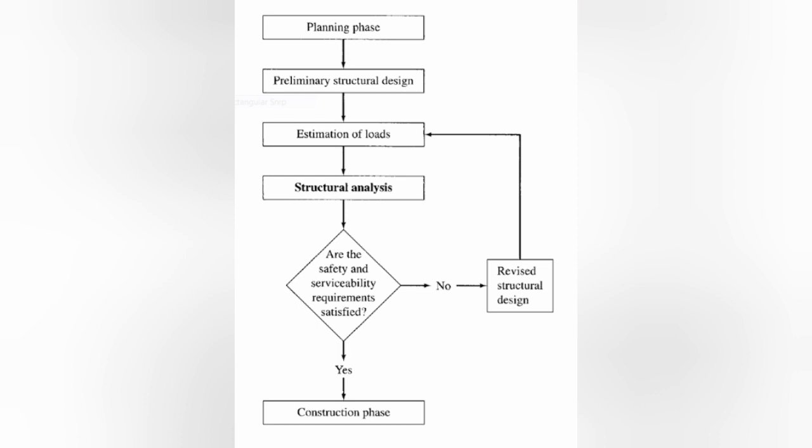Once you have determined those, you can have the safety and serviceability checks. So you can check if it is safe, because in the codes we have minimum requirements. You check whether the stresses and deflection satisfy the minimum requirement for safety.